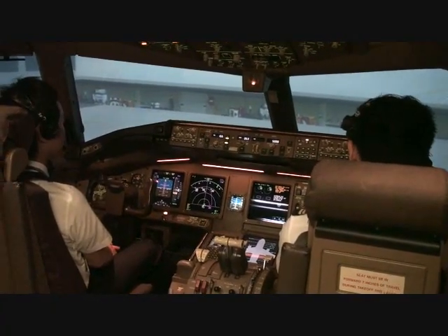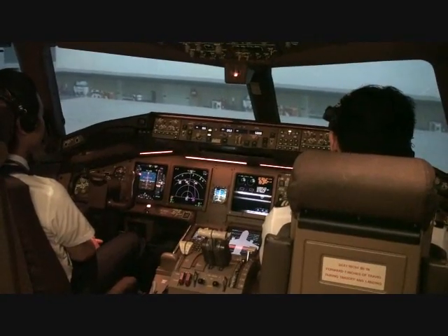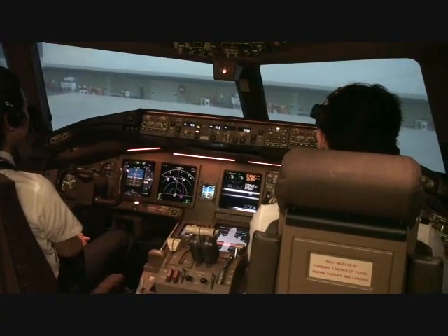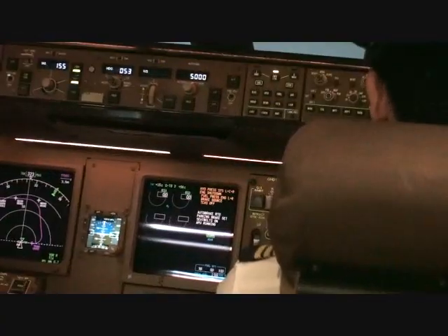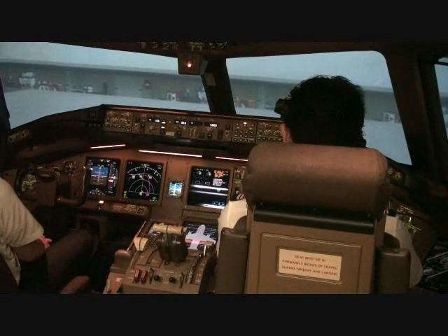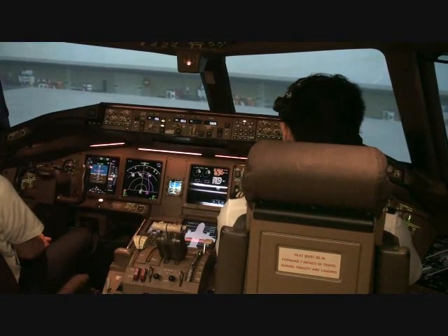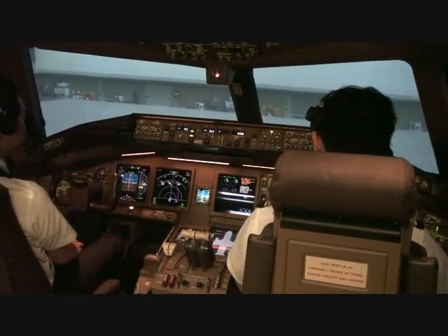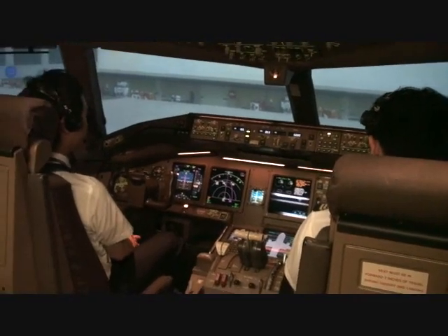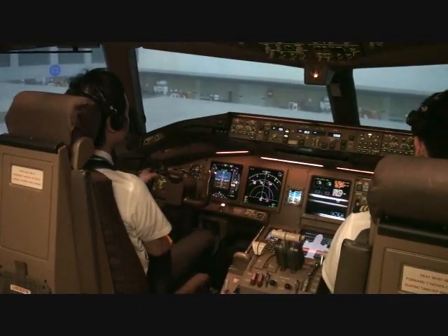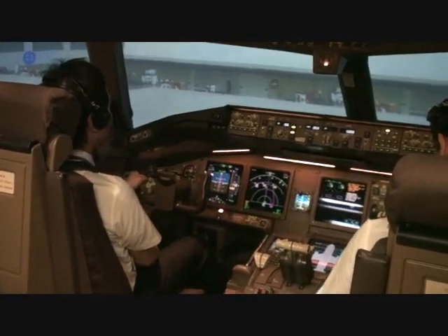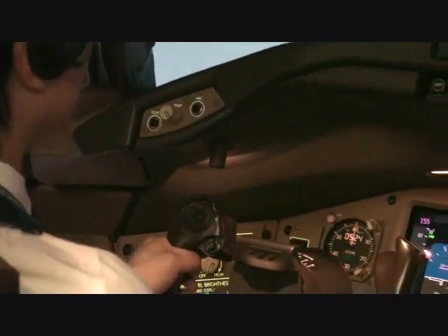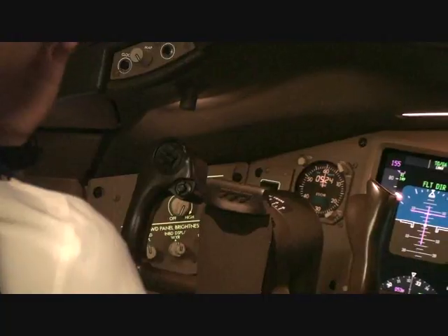Cabin secure signal received. Verify that the cabin ready memo message shows on the ICAS. Ground communications established. CM1, verify that all gear alignment pins are removed. Hello ground from cockpit. Cockpit, this is ground, go ahead. Confirm all gear down pins are removed.